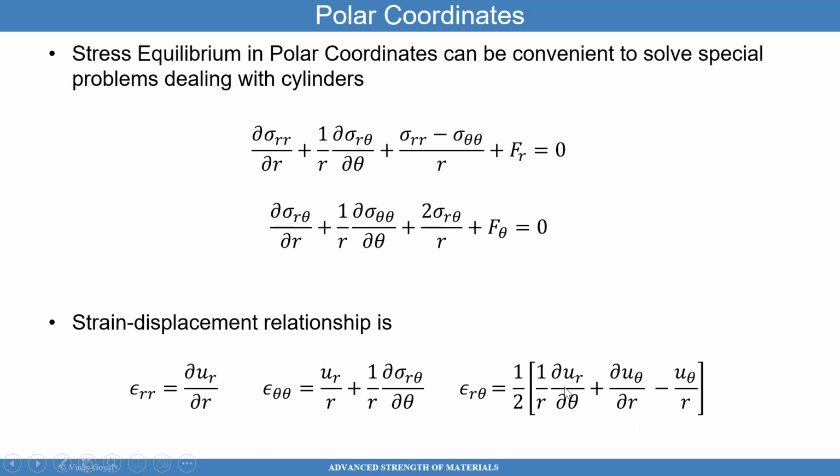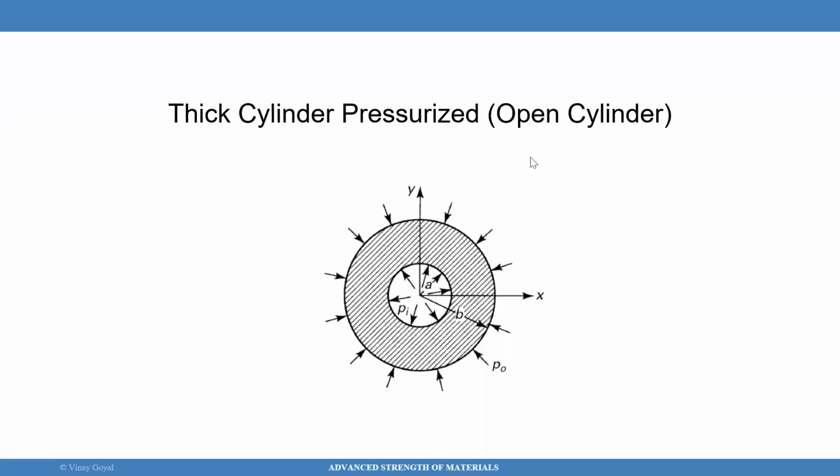Sorry, I have two deflections unknown, as you can see here: the radial deflection and the tangential deflection of a point in a cylinder. So what you see here is you have 8 total unknowns, but yet I have 1, 2, 3, 4, 5 equations. I'm missing 3. And the other 3 equations come from the constitutive law.